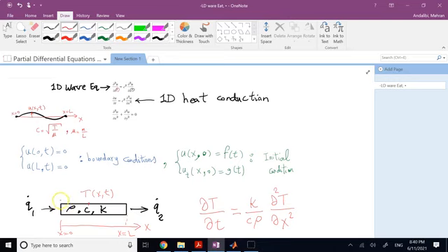Again, the solution of that depends on what you can do to the two ends. Is the heat transfer at the two ends coming from convection, coming from another material through conduction, and so on? And then what was the temperature of the material at time 0? Now here, since the derivative with respect to time is first derivative, you only need one initial condition, but you still need two boundary conditions, okay? So that's the case of this that you see in heat transfer.